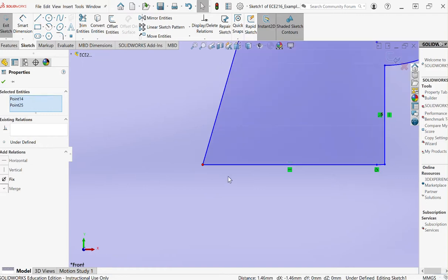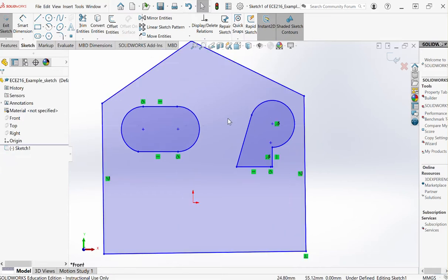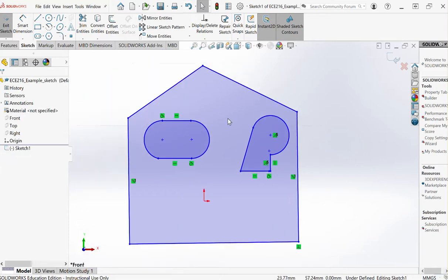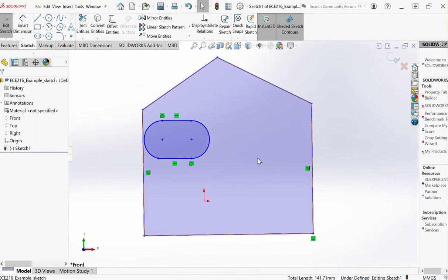If you have a hole in your sketch, you will not be able to extrude or make a cut with your sketch because SolidWorks cannot do that. It's not closed. When it says your contour is not closed, it means that you have a hole somewhere. Okay, so you see everything is blue. I will remove this one because I don't want this shape at all. Let me remove it, and let's do maybe just a circle.